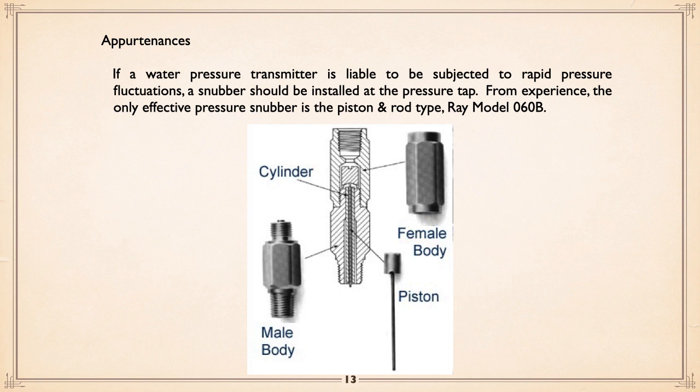The bottom at the connection is where silt will be. Every time the pressure goes up or down, that piston will move, and in doing so, the bottom end of the rod will poke away any debris that's caught. And it's the distance between the rod and the outside of the housing it's in that serves as the snubber. So you can adjust depending on the fluid involved.